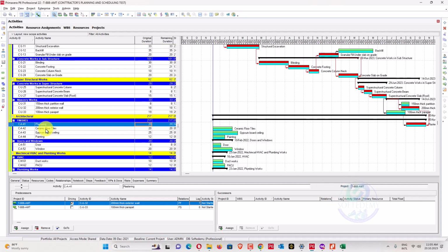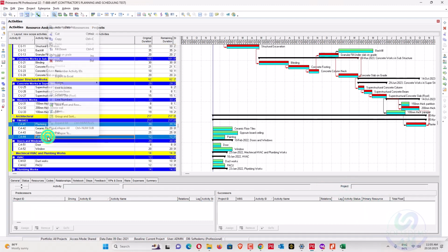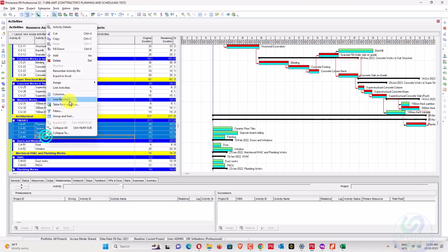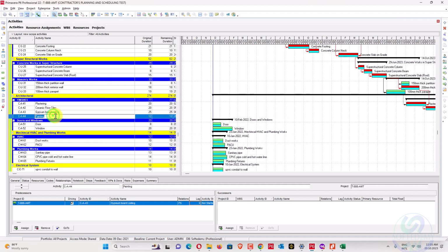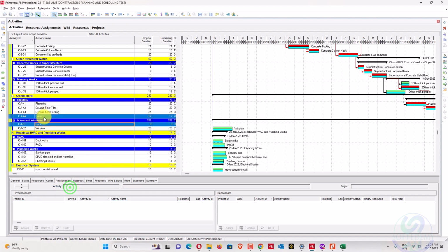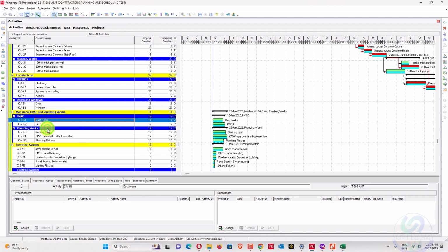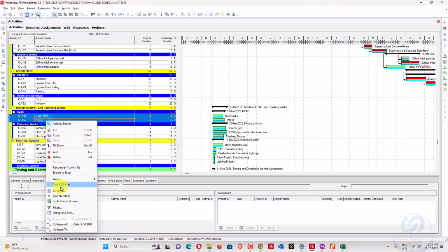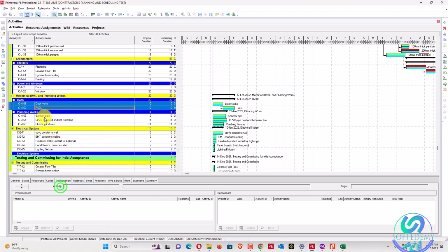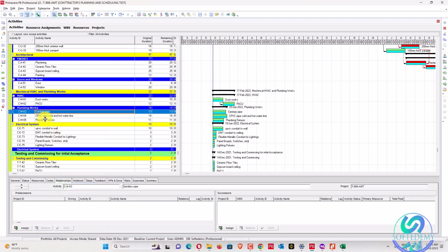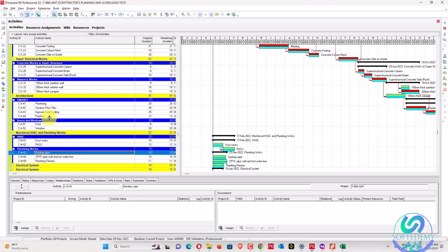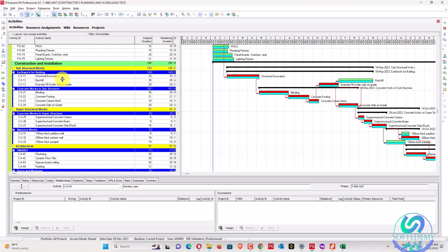What about gypsum tile work? This can be done in sequence like ahead. Link this one. Now what about the door work? Door work can start after the paint work. It's your choice, you can finish that work also. And now what about duct work? After duct work, you can perform your PACU installation, sanitary piping, CPVC conduiting, plumbing fixture. This should be started, which started after the masonry work, parapet wall finish.